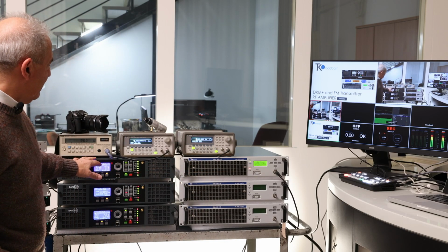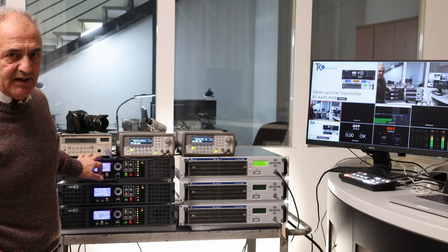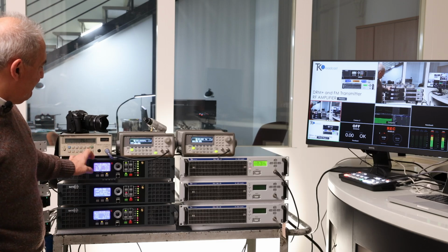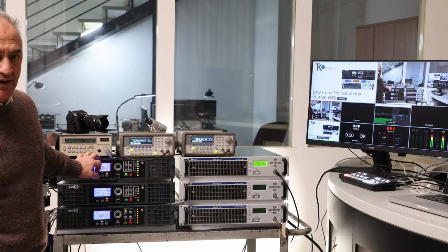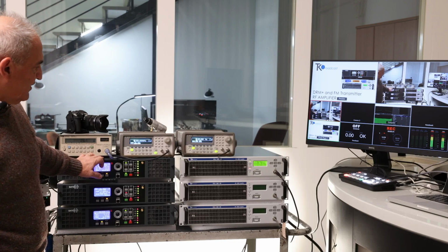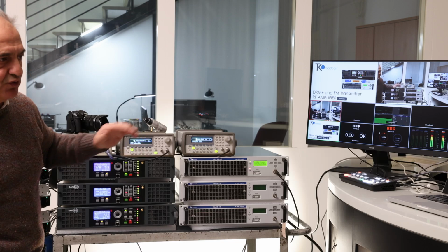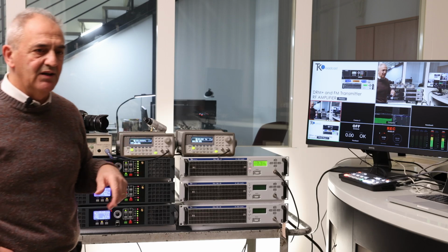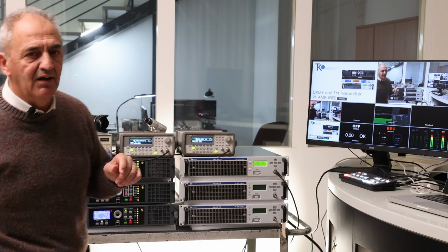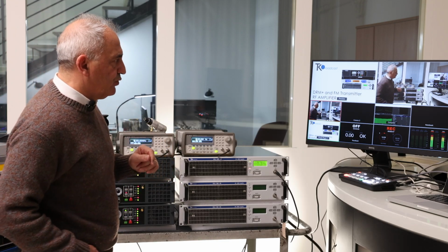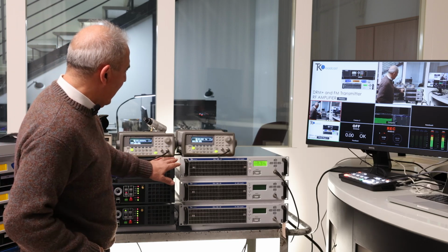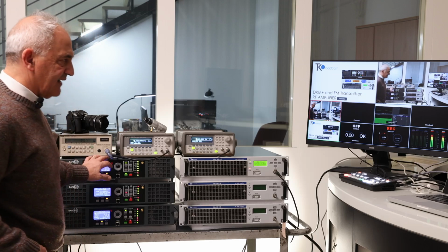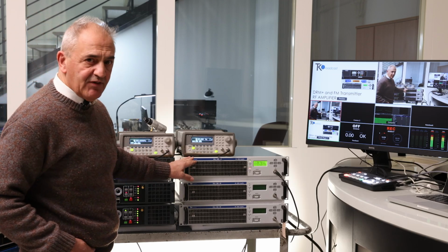Here we have an exciter, a DRM exciter. This can work as FM or HD, iBiquity or DRM. It has a board that is made specifically to take the digital transport stream inside and convert it into RF, iBiquity. To do that, we put the output of this exciter to the input of the amplifier.